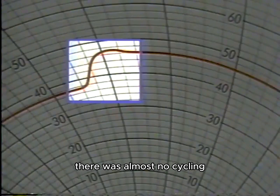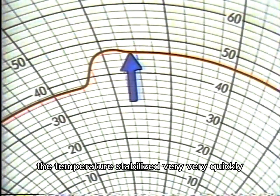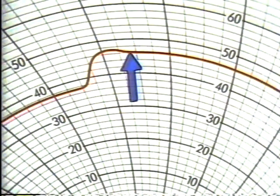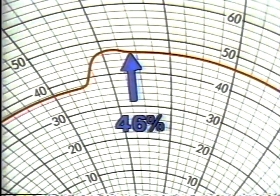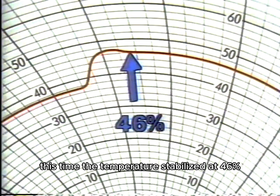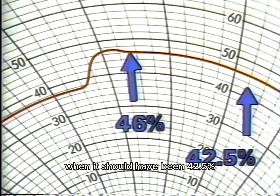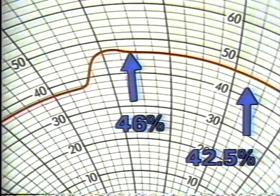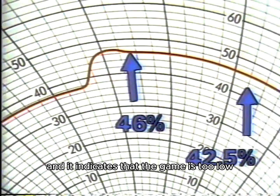There was almost no cycling. The temperature stabilized very, very quickly. And there was a 3.5% offset. This time, the temperature stabilized at 46% when it should have been 42.5%. In this system, this is a wide offset, and it indicates that the gain is too low.